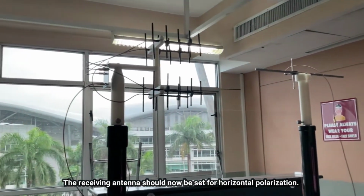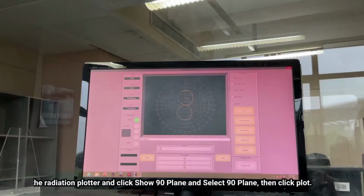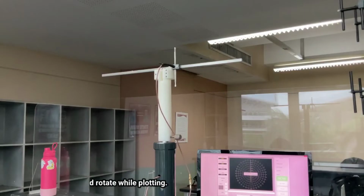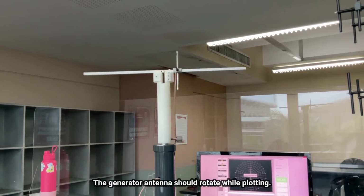Receiving antenna should now be set for horizontal polarization. At the radiation plotter, click Show 90 plane and then click Plot. The generator antenna should rotate while plotting.